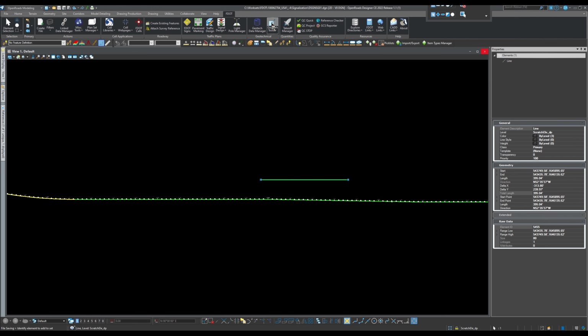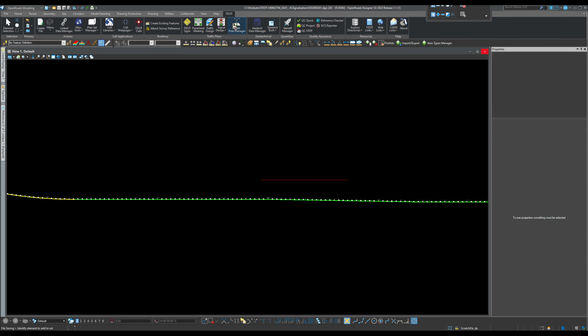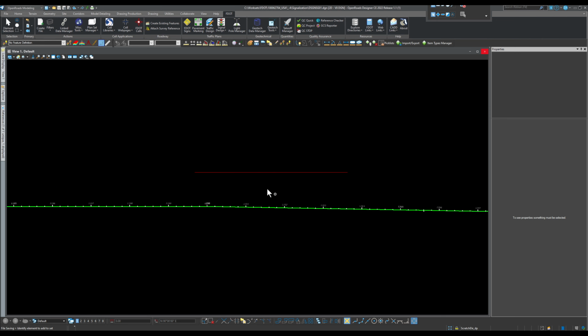And that's how you then run takeoff manager. For example, think of this as a conduit. It will go read the line and then match it to the FPID, the alignment, and the quantity, the pay item number. And then it will spit out a calculation, a quantity in the form of Excel, that is going to be in a calculation folder. So later on, at the end of the video, I will show you how these two run for DOT. We have a PDF about them, we have videos about them, you can go and check them out, but I decided here to show you how to do it another way.